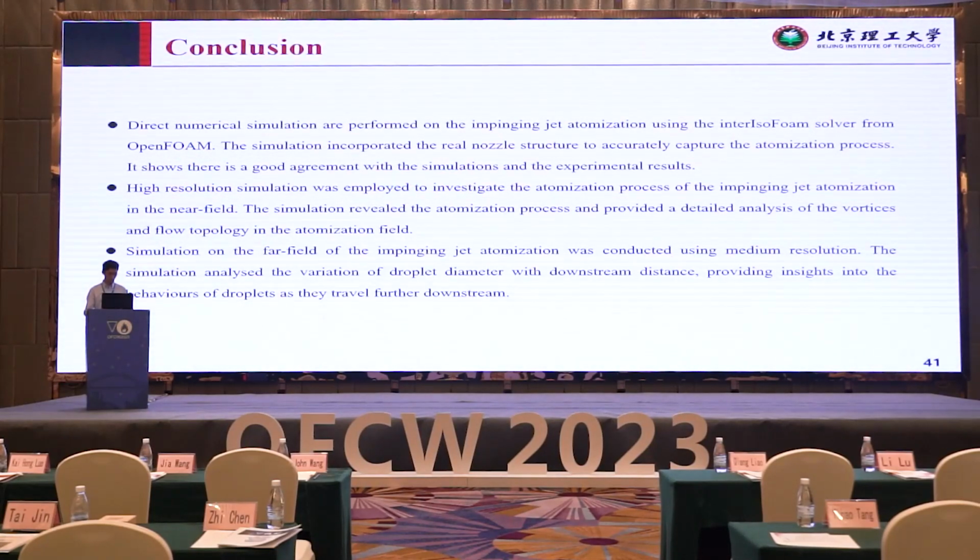In conclusion, direct numerical simulation is performed on the impinging jet atomization using the interFoam solver from OpenFOAM. The simulation incorporated the real nozzle structures to accurately capture the atomization process. It shows there is a good agreement between the simulation and the experimental result, verifying the method. A high-resolution simulation was employed to investigate the atomization process of the impinging jet in the near field. The simulation revealed the atomization process and provided a detailed analysis of the vortices and flow topology in the atomization field.